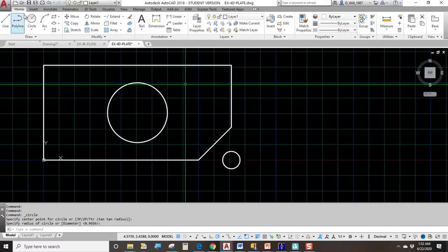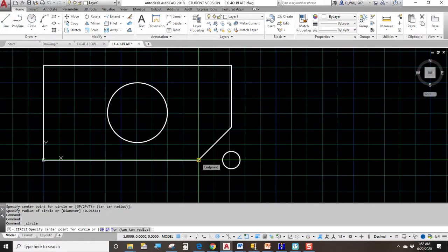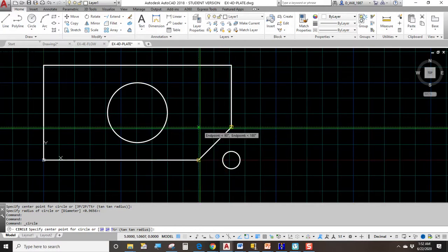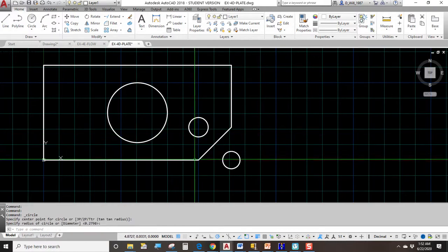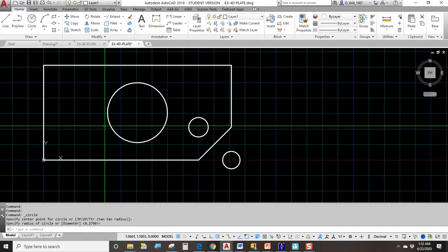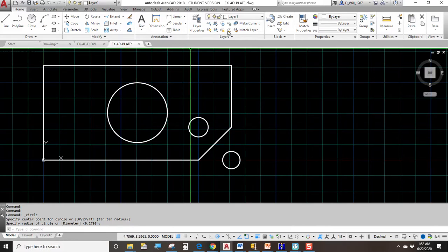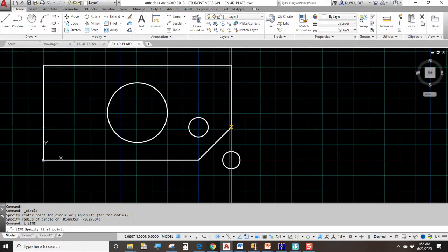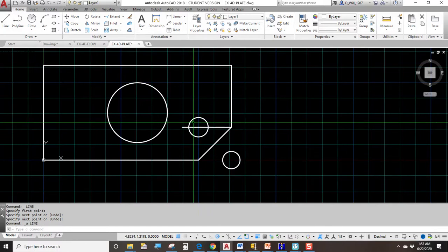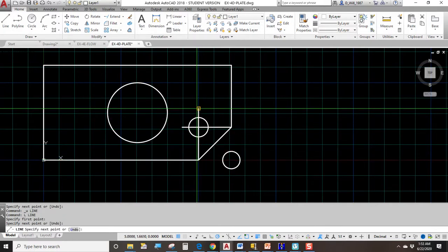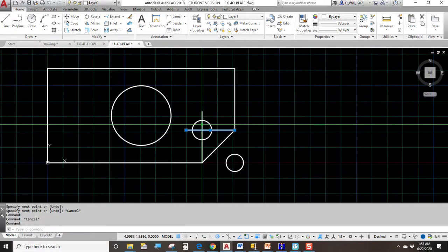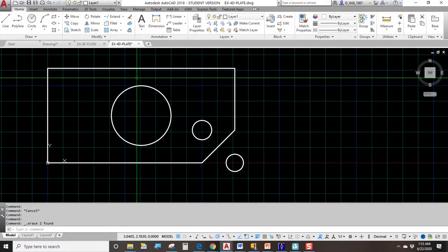We can do it on the inside too. Let's do it on the inside also. Let's find that point there. Let's acquire this point here, and let's slide over until we find the natural intersection of those 2 corners. So, Object Snap Tracking is supposed to help you so that you don't have to go in there and draw lines to find where to put the center of your circle or where to start a new element of the drawing that has to line up with something you've already made. Okay, because these lines usually have to go away afterward, right?